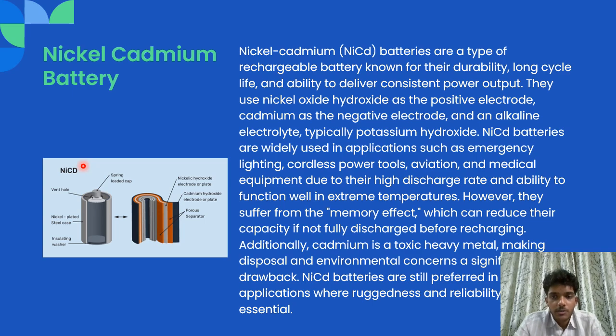Nickel-cadmium batteries are widely used in applications such as emergency lighting, cordless power tools, aviation, and medical equipment due to their high discharge rate and ability to function well in extreme temperatures. However, nickel-cadmium batteries suffer from what we call the memory effect. Memory effect is due to partial recharging of a nickel-cadmium cell. Due to this, the nickel-cadmium cell then won't fully recharge in its next charge as it remembers the previous charge to be its full charge condition.